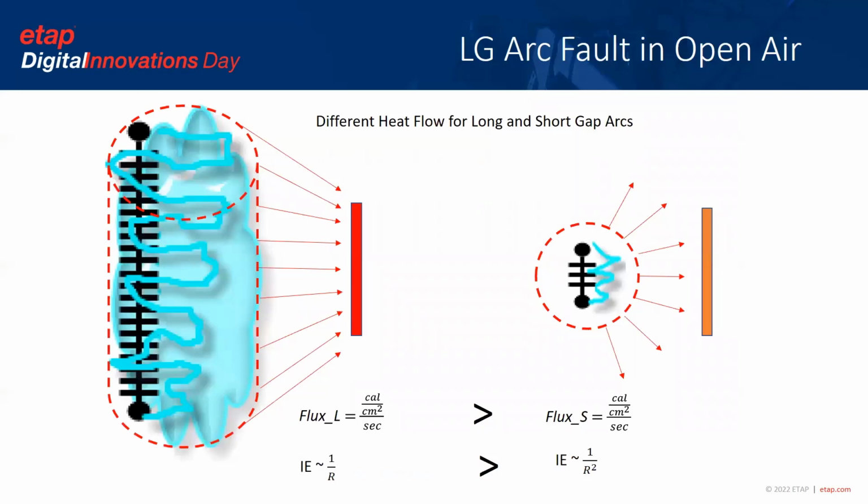This slide shows the main effect of the physical behavior of the high voltage arc from the previous video. The main takeaway here is that the shape of the expanded arc column and plasma for the high voltage arc resembles mostly what we can call a cylindrical shape. The shape of the arc plasma using more familiar industrial methods such as IEEE 1584-2018 is essentially spherical.